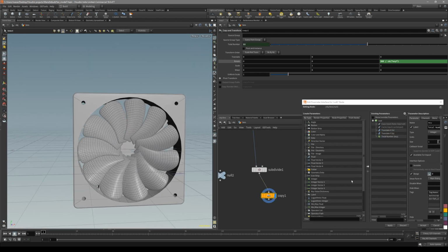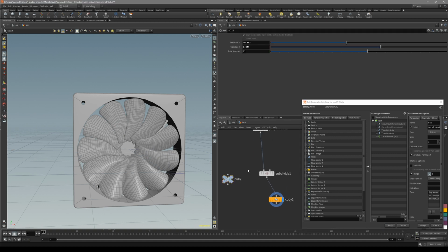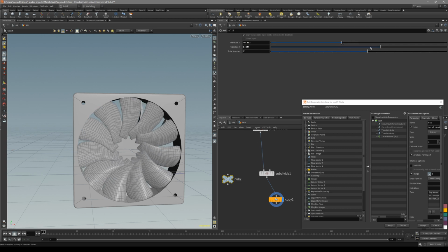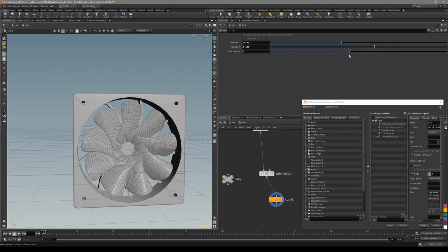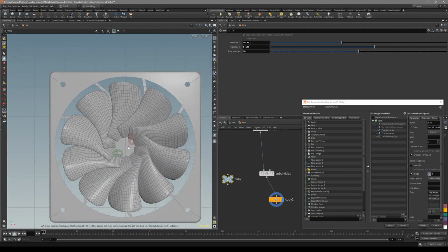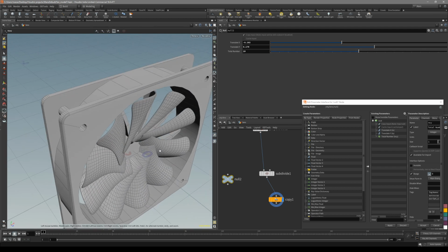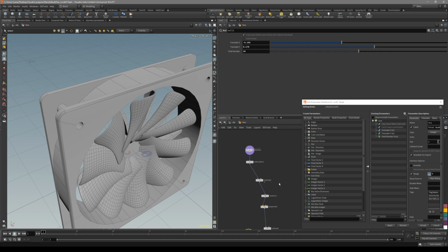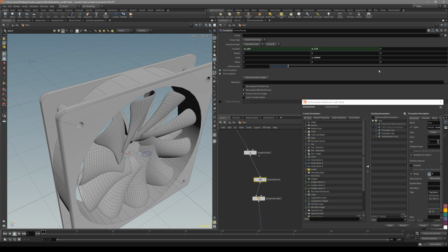Once we have created our controls, for now just press apply and all of our controls are going to be on a null node. We just created these inputs like this, so now you can control like that. Also, one thing, we might want to control the z direction, so just go to the transform and put down z in here, so we can control all three axes.